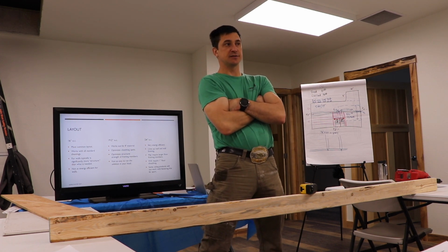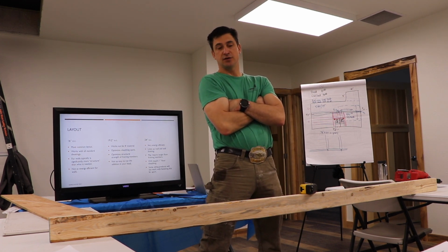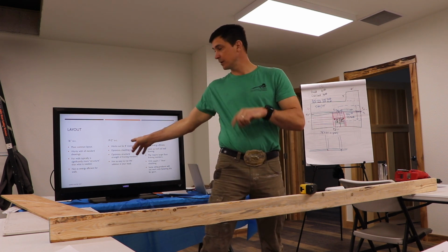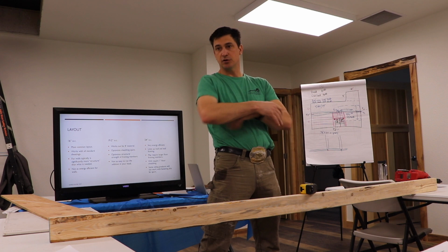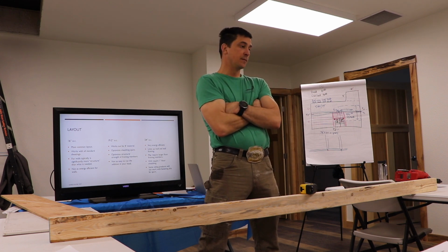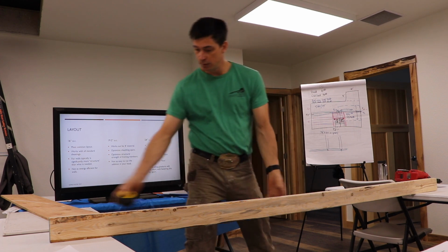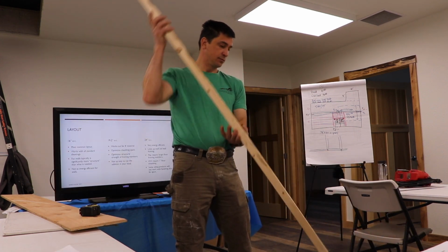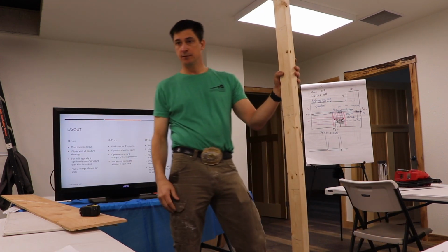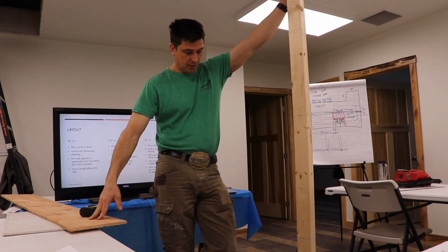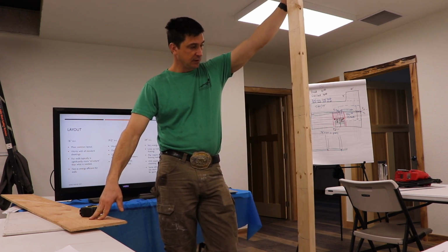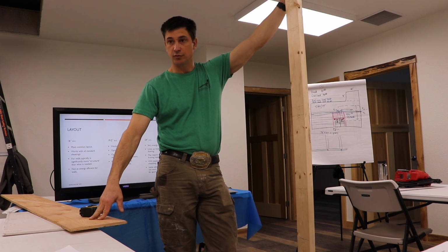Structurally, if you're running at a 16 on center layout and you got one 4 inches away, you don't need it. Like structurally, when we have the class on the building codes, if you have a 1-story house where this wall is carrying the load of one roof, a 2x4 stud is fine at 24-inch spacing.